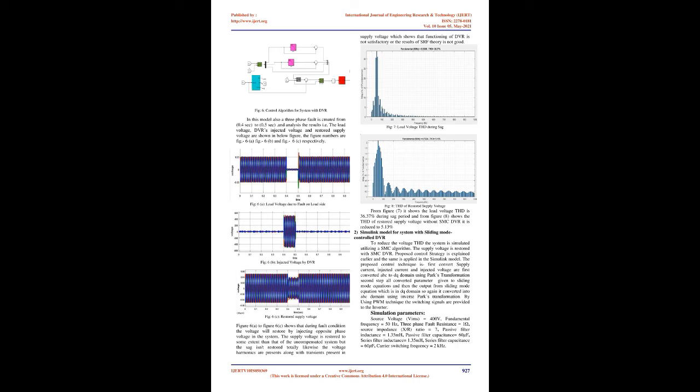The control technique is based on the SRF theory, i.e. synchronous reference frame theory. The control technique is based on Park's transformation, i.e. converting ABC parameters to DQ parameters for easier control, and inverse Park's transformation to convert DQ to ABC parameters. We can independently control active, D, and reactive, Q, components of current and voltage. This is shown in figure 5.